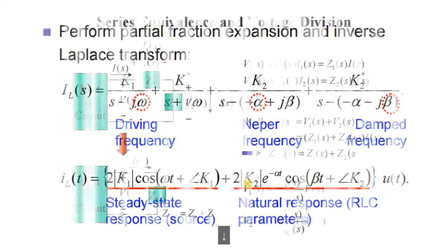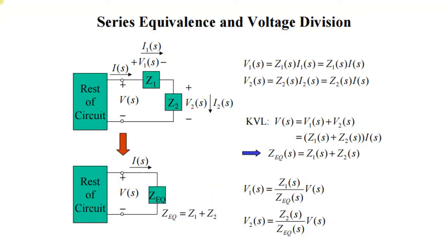And also we see some direct substitutions in the Laplace domain. If it is a series circuit and I want to find the value of V1 or V2, just apply the voltage division technique that we used in the DC circuits. It is very simple, but we take the Laplace transform here. That is the difference; otherwise, the concept is the same. Just use the voltage division technique to find the value of V2 or V1, whatever it is.